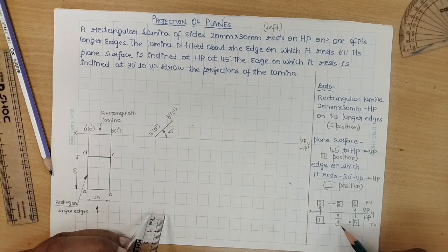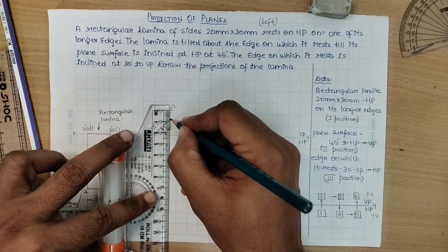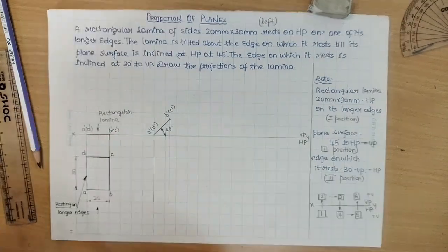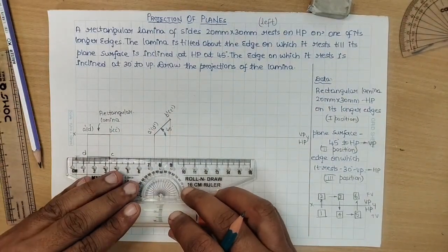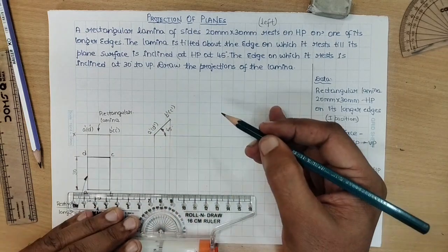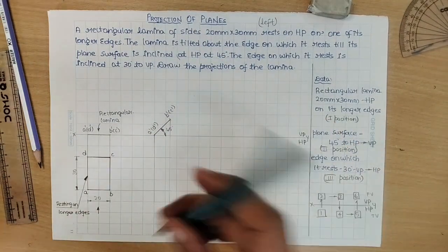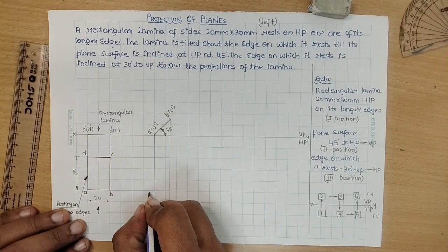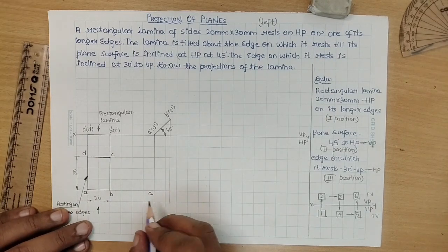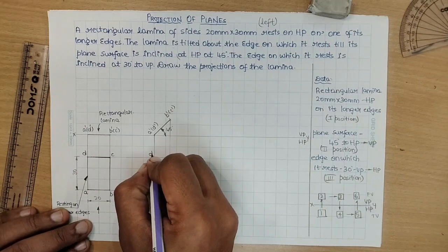To get the drawing number 4, draw a projection line from the point A and D, also the projection line from the point B and C. Now, draw the horizontal projection from the point D and C, also the horizontal projection from the point A and B. Projection from the point A and A both will intersect at a common point, that is point A. Similarly, this would be the point B followed by C and the point D.